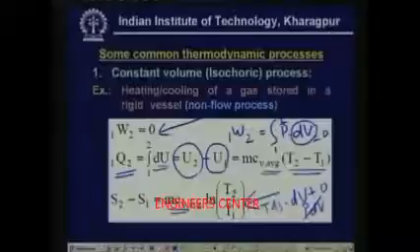Over a temperature difference which is not too large, its volume remains constant, and the heat transfer rate during that process is simply equal to mc into delta T. For a solid, specific heat at constant volume and constant pressure will be the same. So it's simply m c_p into delta T, and the entropy change S2 minus S1 is nothing but mc ln T2 by T1. Okay.